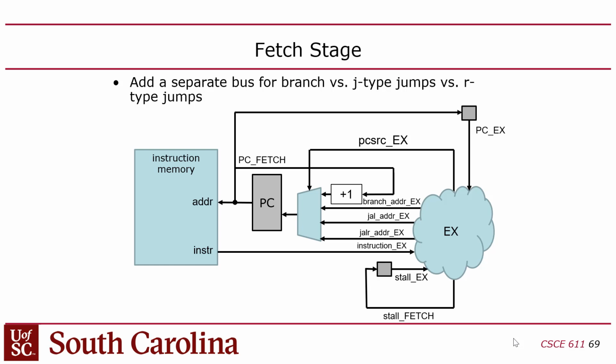Option 1 is you can just always execute it, meaning that whatever instruction appears in your code immediately after any branch or jump is going to be assumed to be executed regardless of the outcome of the branch. That's called a branch delay slot, right? Early MIPS processors used branch delay slots.